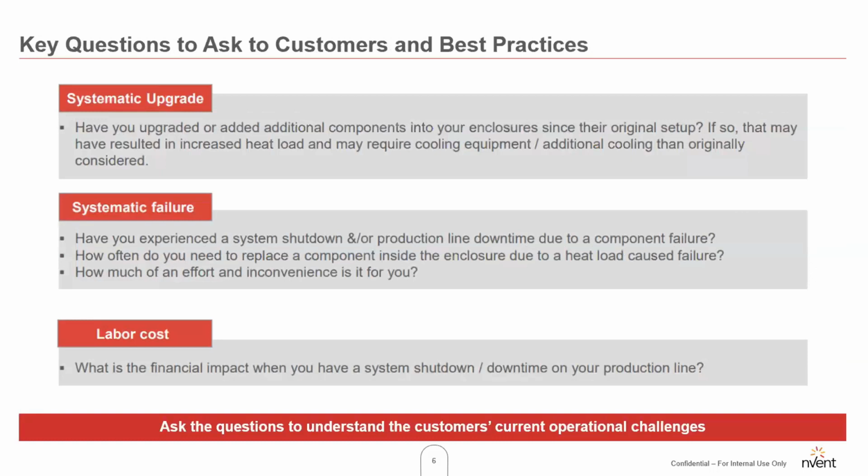Some key questions to ask and some best practices for thermal audits. It's really important before you start doing a thermal audit to understand the customer's facility and what pain points they may be having. Before any audit, I always like to sit down and meet with the customer for five quick minutes just to get a quick rundown of the facility and identify which enclosures may have issues overheating, new production lines that may have been built, drives added to panels. That way you can get a better idea of the facility, and the more information you can gather, the better.